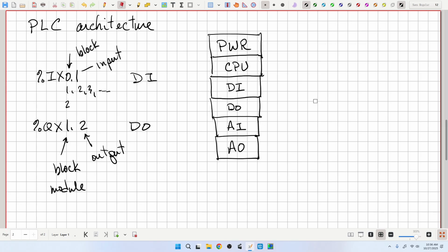For analog signals, we need a standard for, say, voltages and or currents. Pretty common standard voltage range would be 0 to 10 volts, although you could have a shifting of that, but that's fairly common. So inputs from 0 to 10 volts, or if there were currents, pretty commonly you'd have 4 to 20 milliamps.